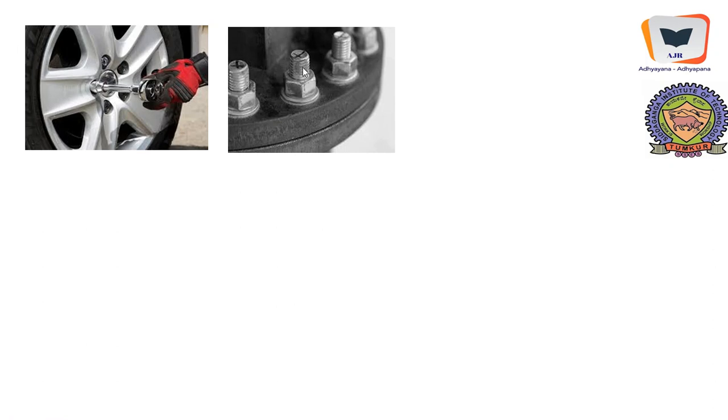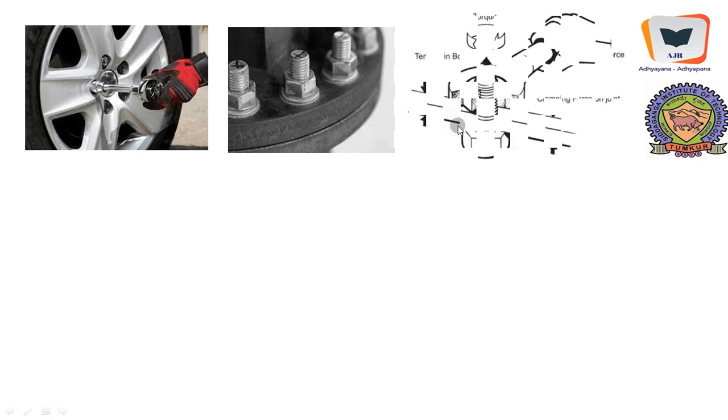When we rotate this nut clockwise, this stud will be subjected to tension while these two pieces will be fastened tightly together. And if you remove this system and had this been a wooden ring-like thing, we would have seen impressions created by this washer. That means this member will be subjected to compression while the stud will be subjected to tension.